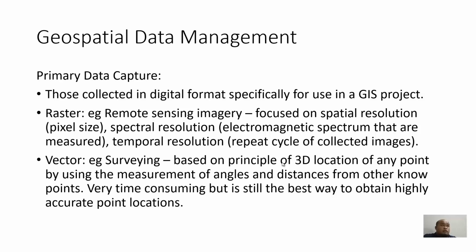If you use a total station, you will just be able to collect about 1 point per minute, at the fastest 1 point per minute, or 30 seconds per point. Yeah, if you use LiDAR, you can capture about 1 million points per second. Similarly, with the terrestrial laser scanner, about 500,000 points per second. Yeah, those are the surveying equipments.